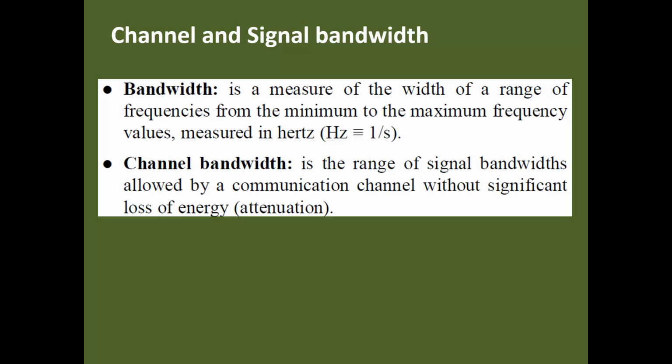All right. And what is actually the signal bandwidth? Signal bandwidth is that within which we place the signal. For example, if the signal is a baseband, let's say a speech signal, the bandwidth of the speech signal ranges from 300 hertz to 3400 hertz. So that is the signal bandwidth within which we place the information. Now that signal travels through the channel, and how much bandwidth the channel offers to the signal is what ensures that a respectable signal strength is achieved.